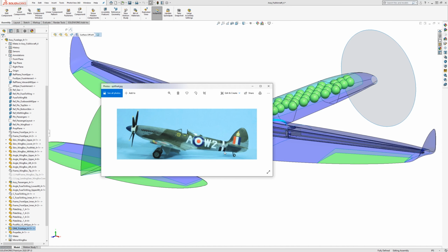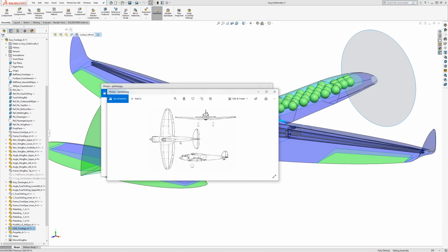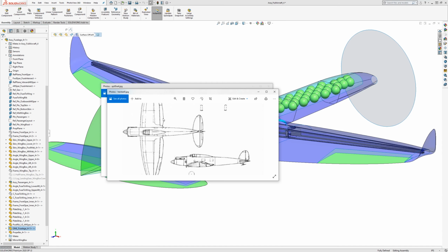So that's one of them, but there are definitely others. This is another plane with an elliptical wing. This is a Heinkel 70, and you can even see that near the root they decrease the chord length. So this fairing is much smaller. It looks like the radius is about the same along most of the length of it.